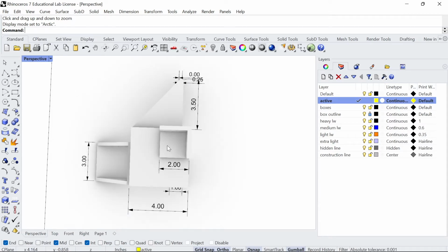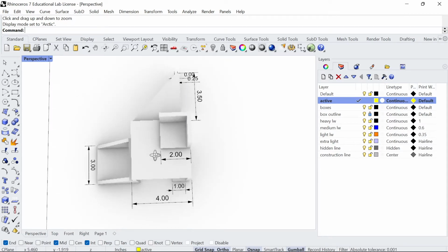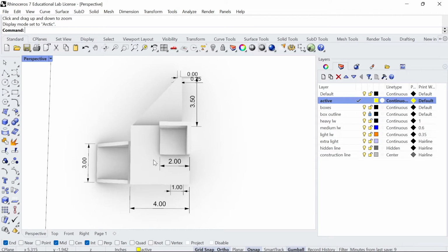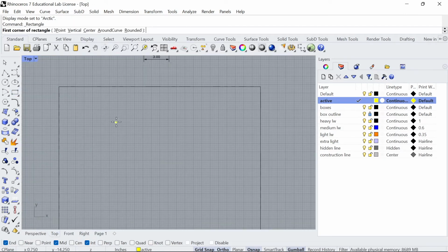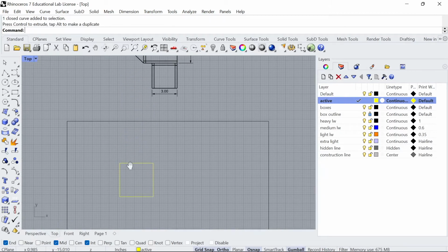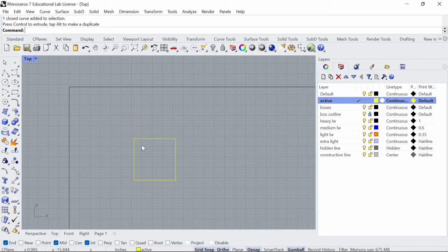Okay, so I'm going to try to attempt to draw something like this. So in front of you, you're looking at something relatively top view like I am here. It probably looks something like this in your real perspective with your eyes. Okay, so I'm going to go ahead and go to top view again. What I'm going to do is attempt to draw the 4-inch square. So 4 inches by 4 inches, just by using the rectangle command right here, you get a 4-inch square. Okay, I'm not going to worry about line weights right now. We'll set that up a little bit later.